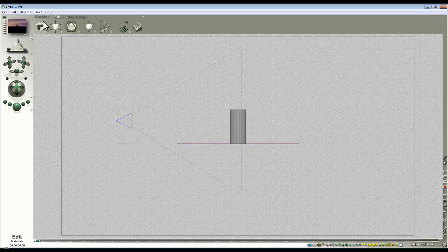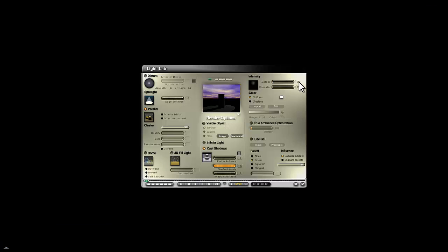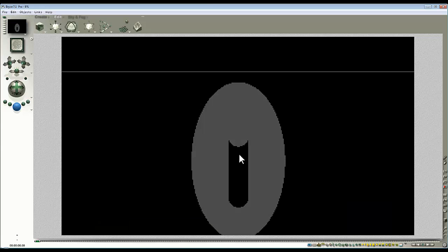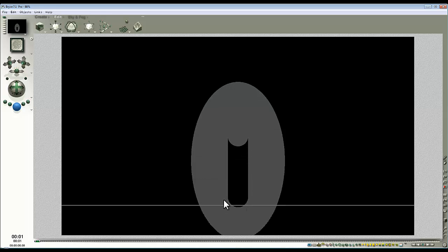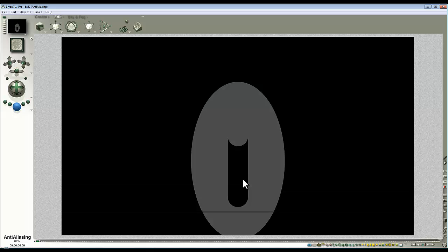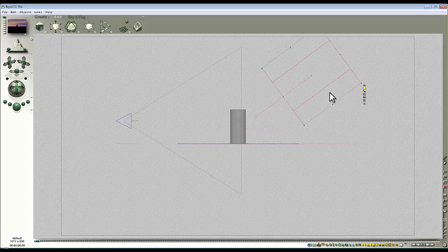Okay, those things apply to the new light sources on the crate shelf. So we've got this round parallel light and square parallel light. They operate in very similar ways. So let's pick this one. Right, so this is the new parallel light and it does in fact behave correctly, I'm pleased to say. So I'll get this set up as I did the others and edit it. Reduce its intensity but turn the falloff to none, and then switch back to the main view, and you can see now the shadow is perfectly parallel, of equal width, and the light arriving on the ground is uniform, so that's a really good sign.